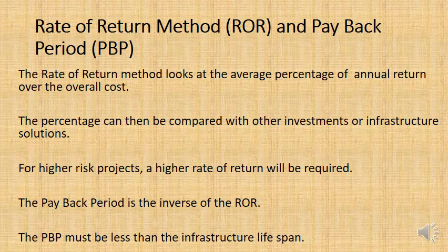And for a project to have any chance of being viable and feasible, the payback period must be less than the lifespan of the infrastructure in civil engineering. So if the payback period for the dam, let's say, is going to be 40 years, but the dam itself is only going to last 30 years, you would not build the dam.